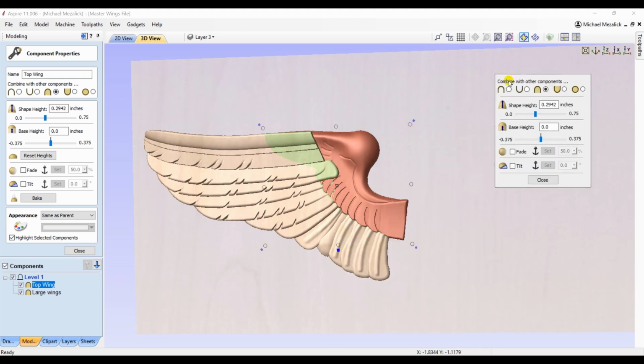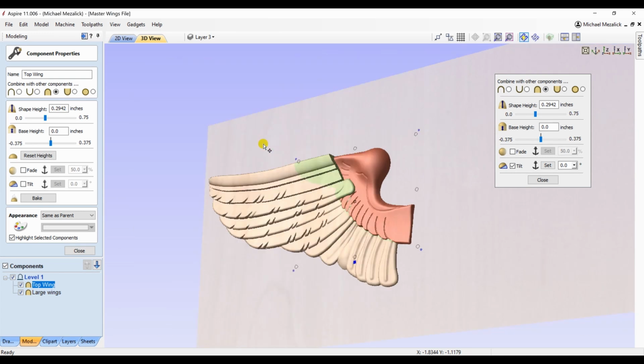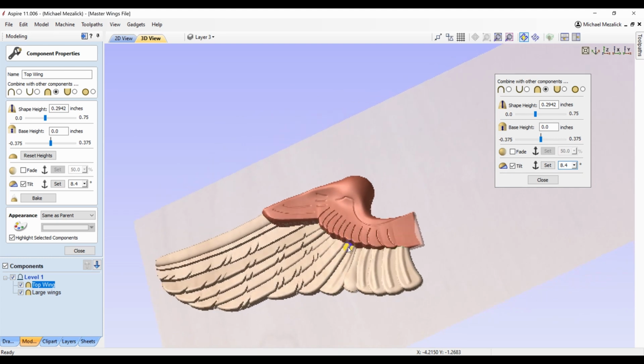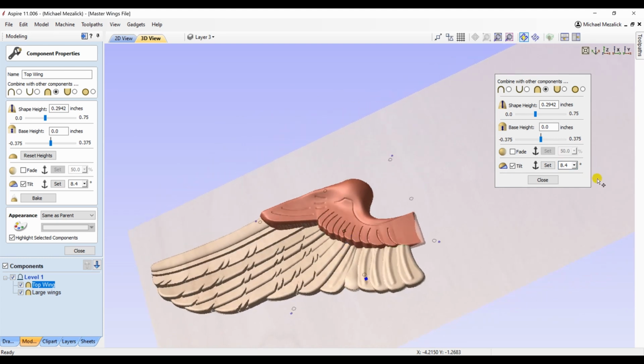Click on the little blue square, open up the interactive property window, and I'm going to tilt from the right-hand side to the left-hand side. Remember, tilt is always in the up direction. I think that's what I'm going to choose. I can work with this. I may just reduce the tilt ever so slightly. And I think I'm going to increase the base height.